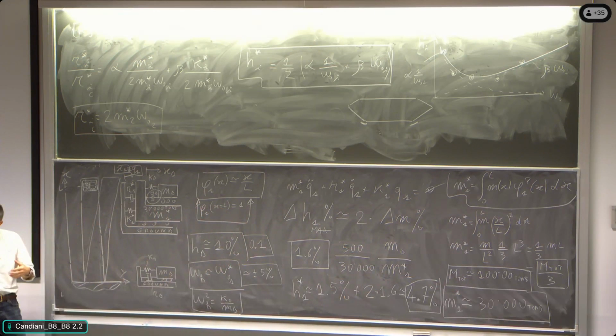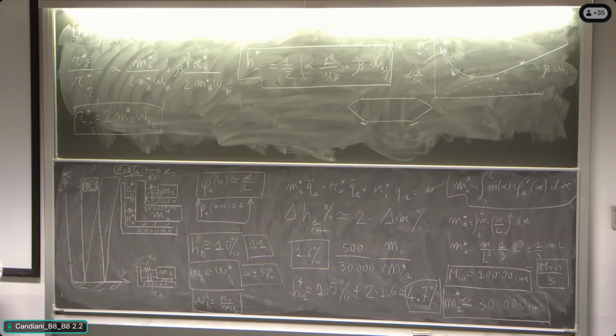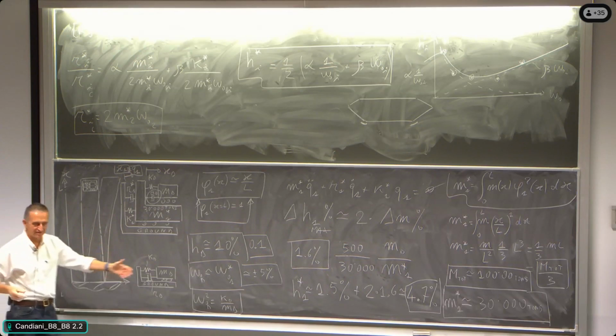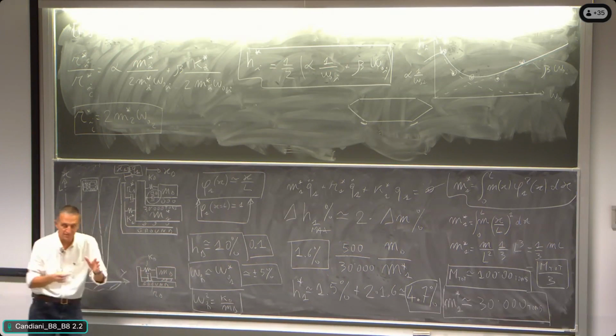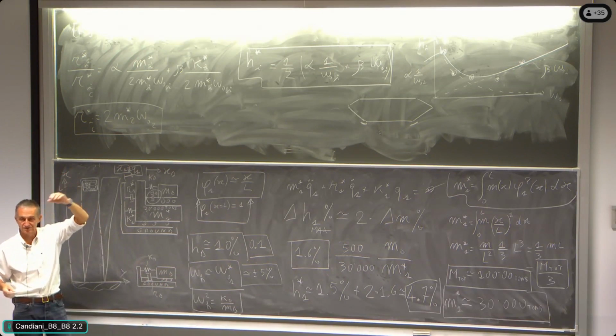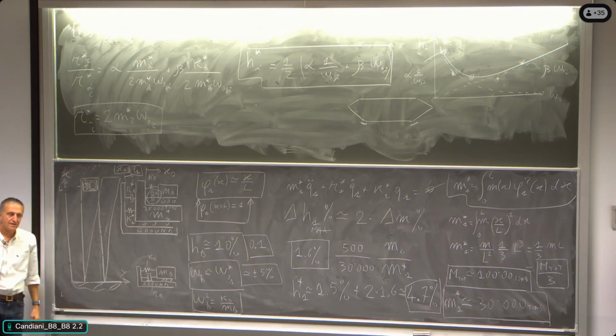and so the idea, if you are looking at the buildings, if you ask ChatGPT which are the dimensions of the tuned mass dampers of the buildings around the world, it will tell you numbers like that, some 100 tons, typically. The reason is that it is more or less the total mass of the building, but we speak about buildings with a height of 200 meters. So if we speak about buildings of 400 meters, it's different, all right?